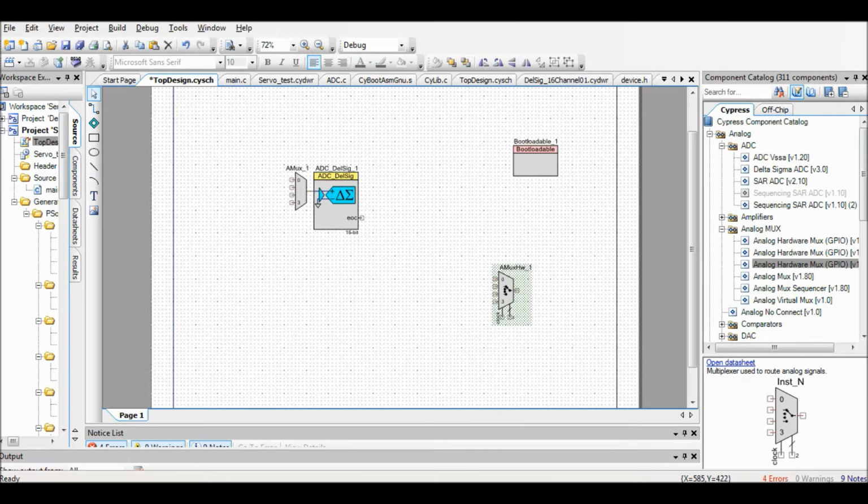So you would write a 1 or 2 or 3 or 0 to this pin, and it would disconnect the previous channel, connect the new one. It would take 2 clock cycles essentially to do it, and it would be doing it separate from the CPU. So it's really useful to certain applications, but we're not going to do it that way. You could also, even probably more useful for this application, would be a sequencer, since we're just switching between 2 channels.